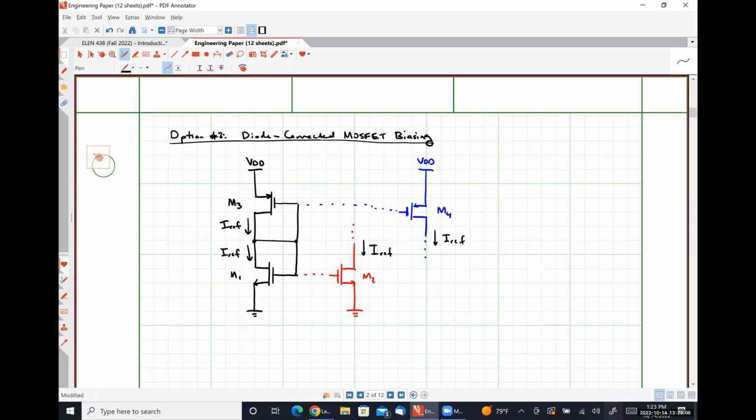So effectively, what's going on here is, let's say that transistor M3 is replacing our resistor from our previous example, so that our current mirror is established by M1 and M2, okay? That means that we would have some voltage here, VGS1, and we have some voltage here, VGS2.